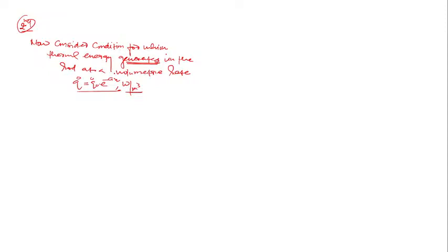Previously we have seen uniform heat generation. Now here is non-uniform heat generation. Why non-uniform? Because it's a volumetric heat generation, qg dot is a function of x, where q naught dot is a constant.